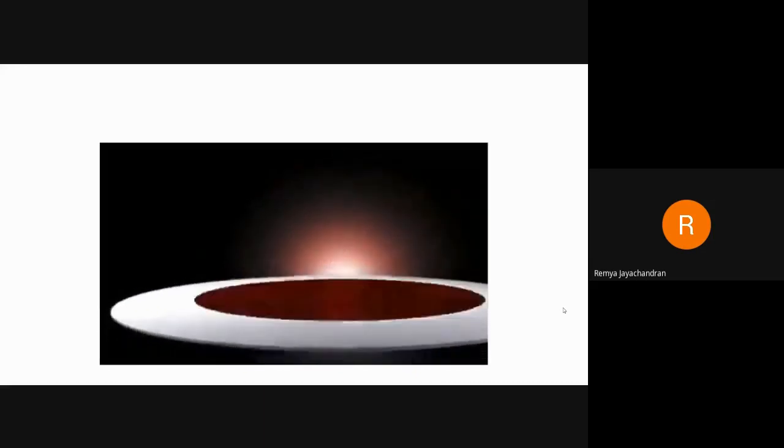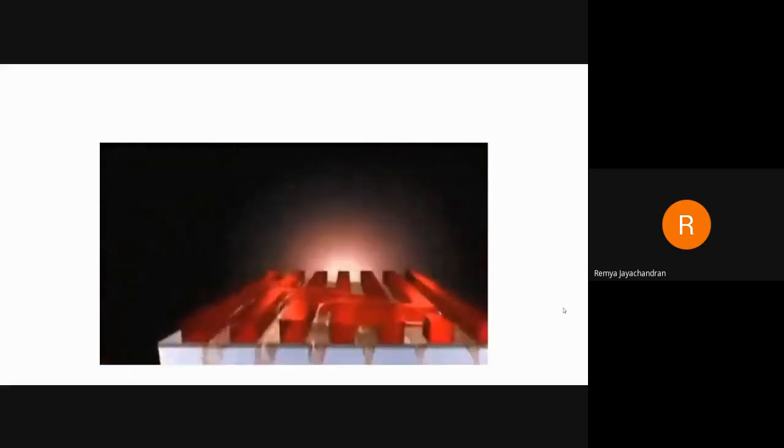The silicon disc is spin-coated with a photosensitive resist. UV light transfers the circuit structures depicted on a mask to the wafer. The exposed parts of the resist are soluble and are removed by a developer. The transferred structures can now be used as a template. The unprotected parts of the wafer surface are etched away. The structures of billions of small current switches are generated on each wafer, tiny transistors.